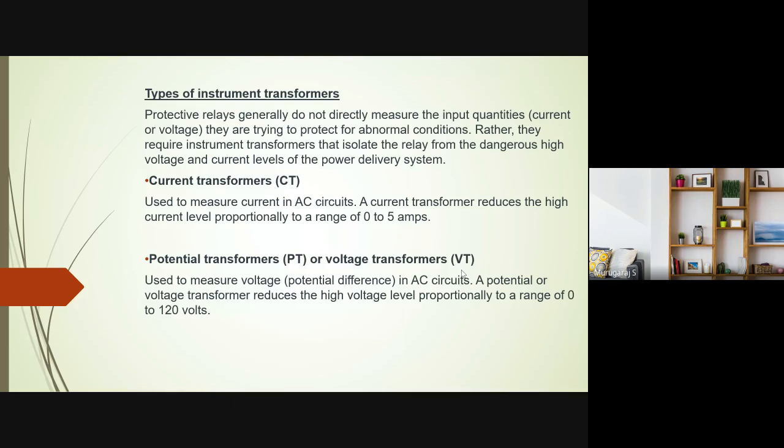So whether the motor is loaded or not connected to a load, it will tend to take starting current because there is no back EMF generated in the secondary side. Once the motor has started, the back EMF is slowly generated in the secondary circuit. Once the motor picks up 80% of the speed, which happens in about 2-3 seconds, the starting current will be there until then. Once the EMF is generated in the secondary side, there will not be any starting current. Then it will be only the rated current.